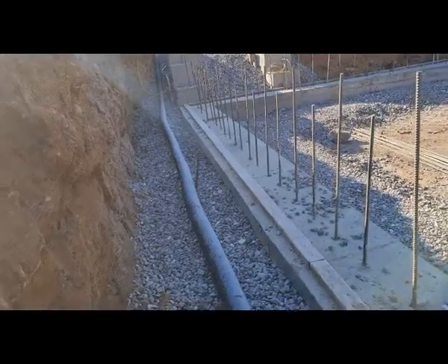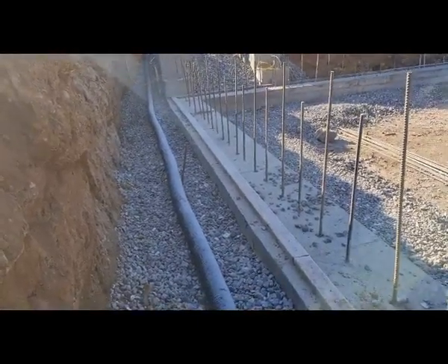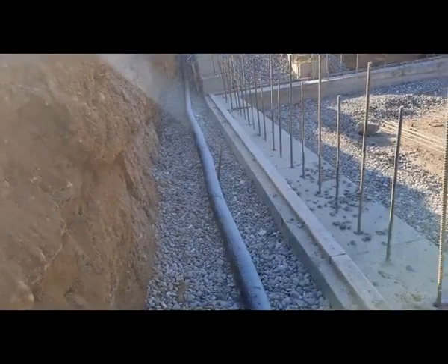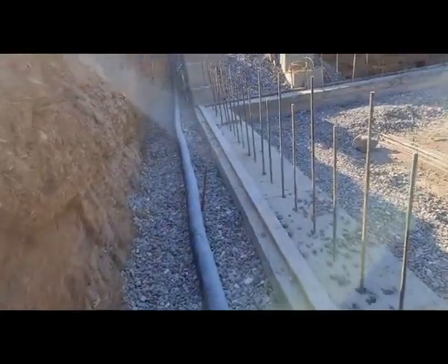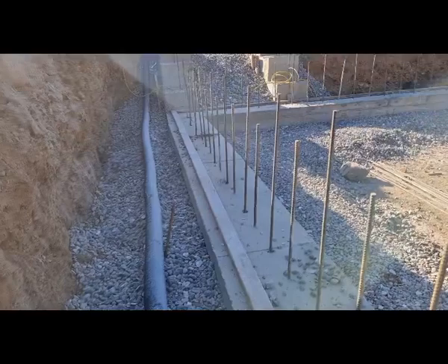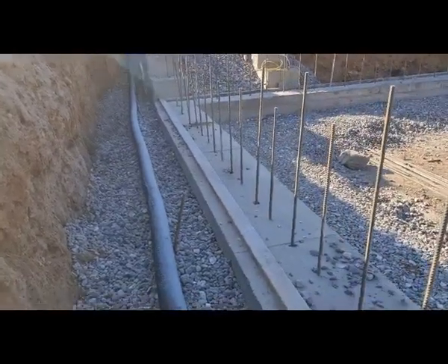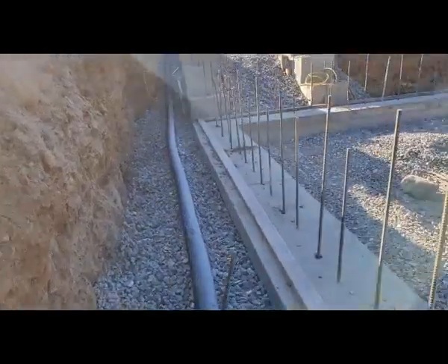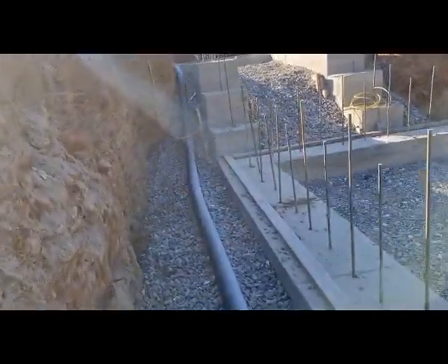You put about 8 inches of stone under the pipe, 8 inches or 12 inches, look at your plan. Then you call for inspection, which I'm waiting for right now. And once we pass inspection, you put another layer of stone on top of it. So as you see right here,